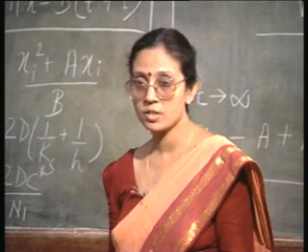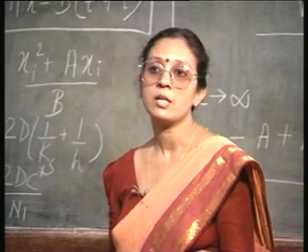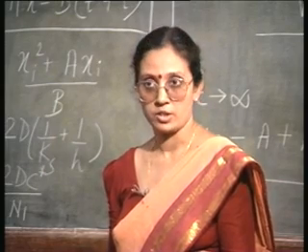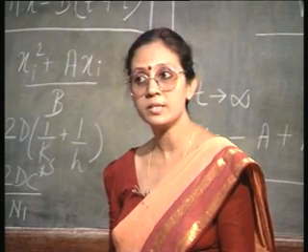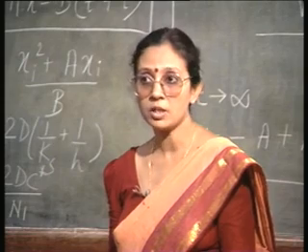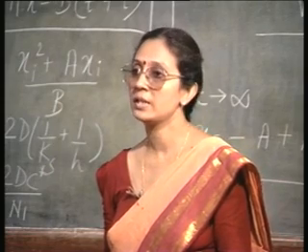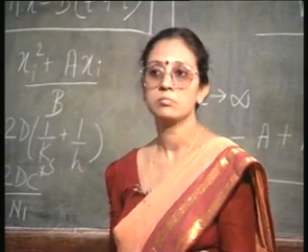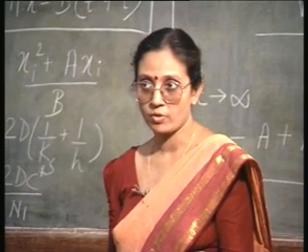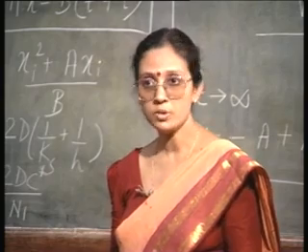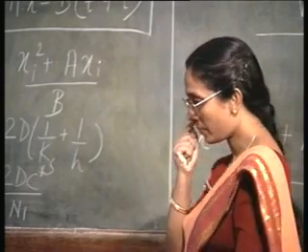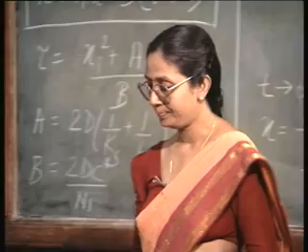So, dry oxidation is used mostly for gate oxidation. That is where you are bothered more about the quality of oxide, not the quantity. You do not want a very thick oxide, you want moderate thicknesses of oxide, but you are particular about the quality, then you will use dry oxidation. Okay.